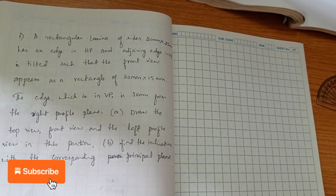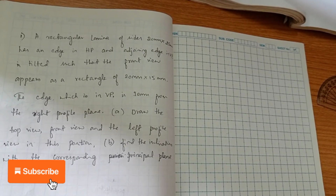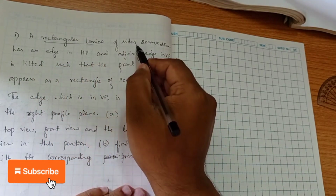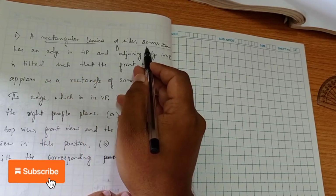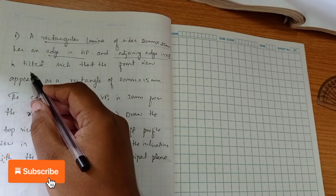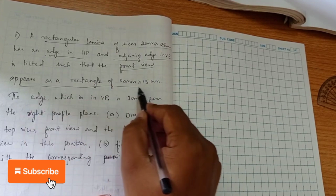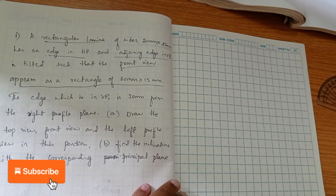In this problem also they have not mentioned any kind of inclinations. So based on the question we have to proceed with the solution. You can see in this question, first we have to construct a rectangular lamina of dimension 20 into 25 has an edge in HP and adjoining edge in VP. So that's our first position. It is tilted such that its front view appears as a rectangle of dimension 20 into 15 mm. So that's your second position. Now I am drawing the first position.